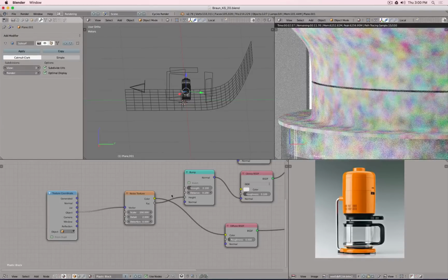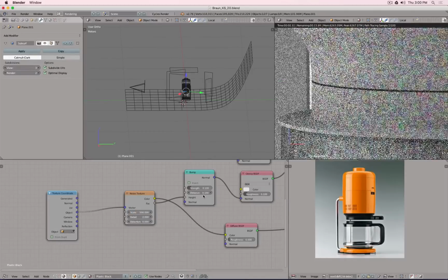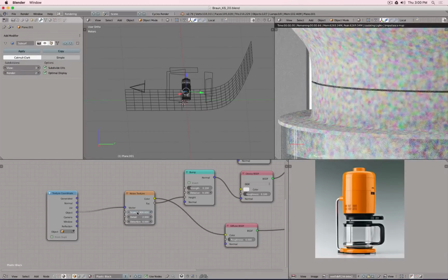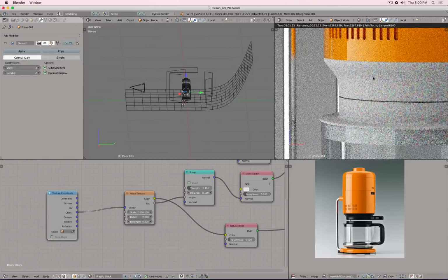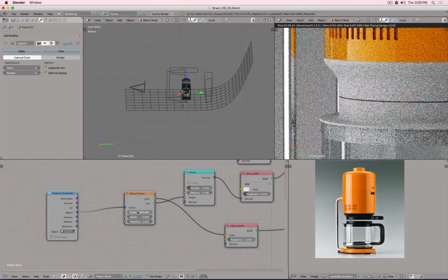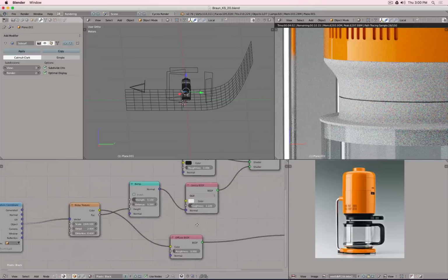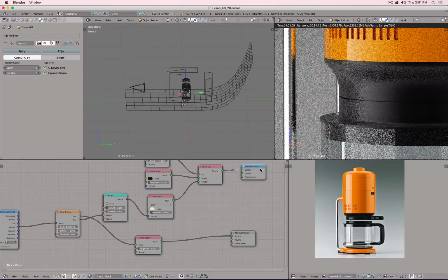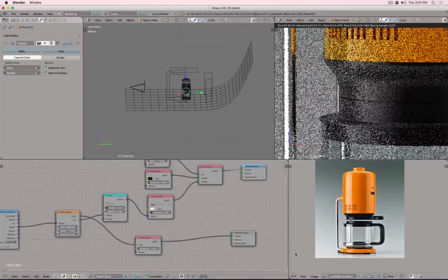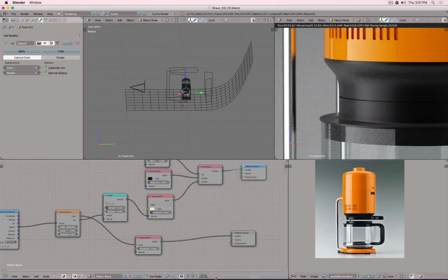And yeah, they're really big, so we might have to scale this one down. 500, still too big. 800, maybe 1000. And you see this pattern size-wise is uniform and nicely flows around our object. 1500. Yeah. Okay, so let's see how this will affect actually my reflection. So I click on material output for this part, and there now I see this pattern nicely. And the size is way too big, so maybe 2500. That's still a little bit too big, so maybe 3000.